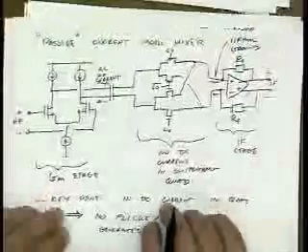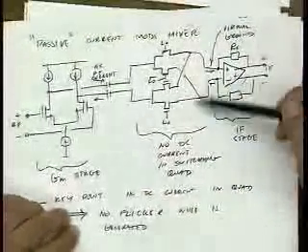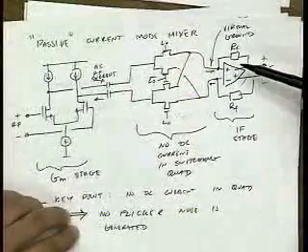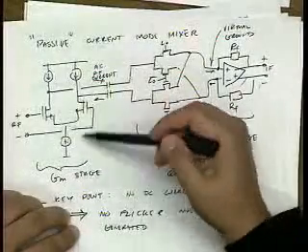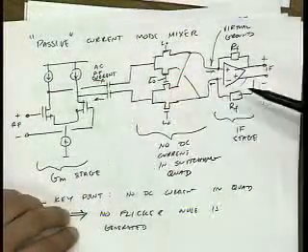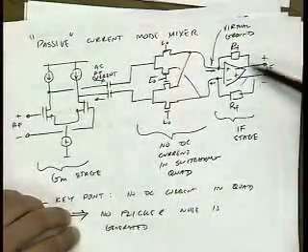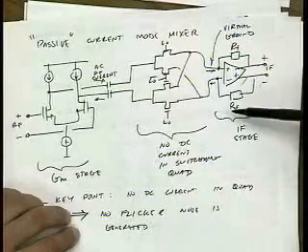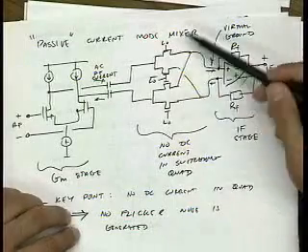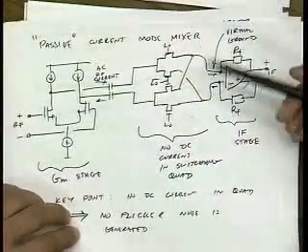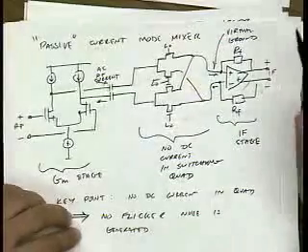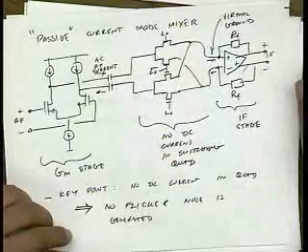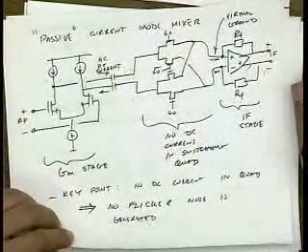So in a way, the current that we saved here, we pretty much have to burn here anyway. So there's really practically no current saving. You're going to need to run current through here, and through here. And to create a low noise op-amp, you're actually going to need to burn a substantial amount of current here. And you need a large LO drive. So from a power consumption perspective, there's actually no win. It's really the voltage headroom that's the biggest advantage that you get. Okay.